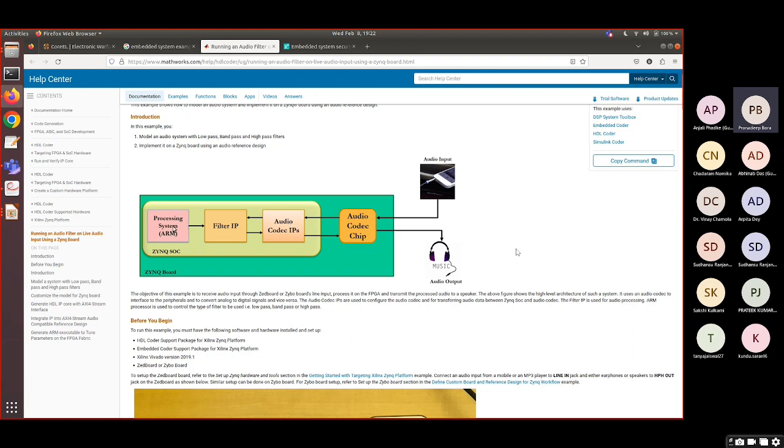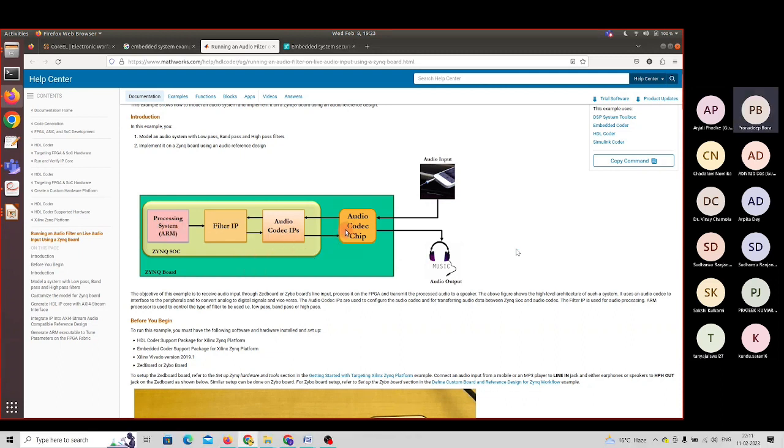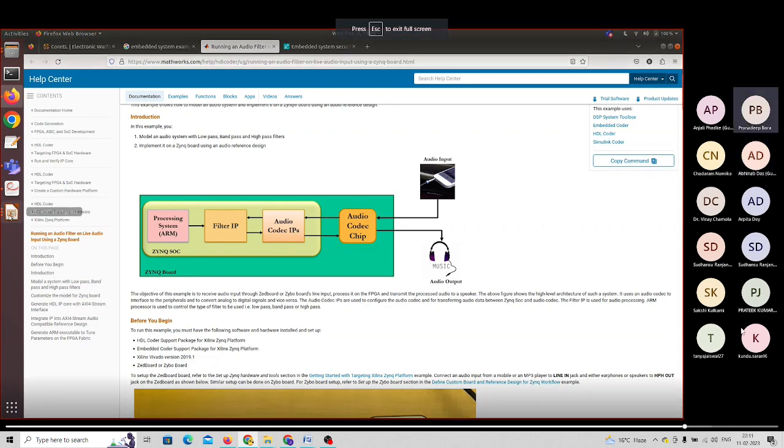The ARM processor is controlling all those peripherals, taking the data, and sending read and write information. The C code to control those peripherals is developed inside the ARM. This is a peripheral IP, this is a peripheral IP, this is connected to this peripheral. That intercommunication part is done in the FPGA fabric. Yes, sir. Understood. Yeah, fine.